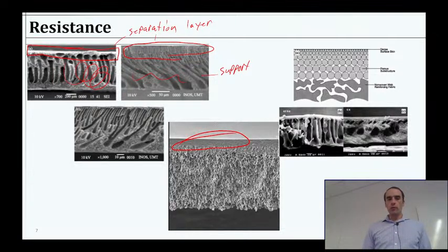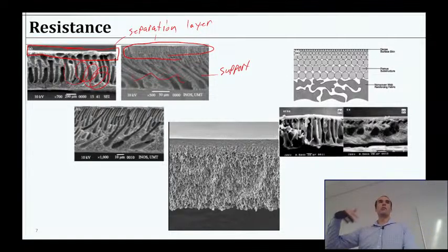Now, as soon as you start filtering dirty water, you're going to start accumulating junk, particles. And as you see, these are not ever going to be perfect little particles with perfect little pores that are going to block them or not. So we're going to have some random assortment of where stuff starts accumulating. And we're going to end up having fouling that we see here, right? So accumulation of particles on top of particles will eventually make its own separation layer unless we clean it off.